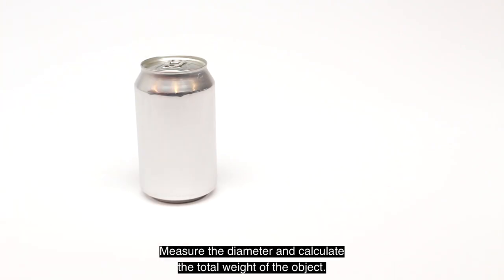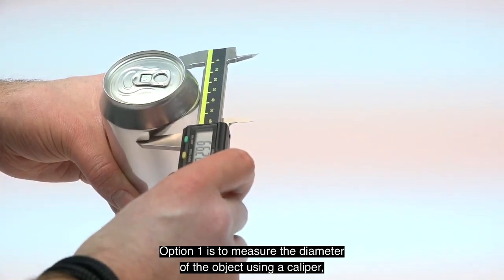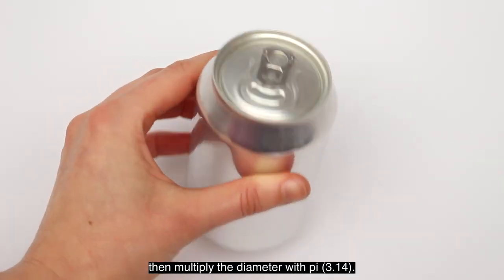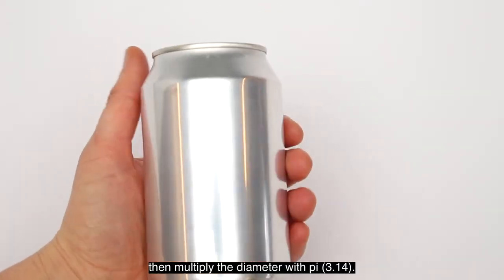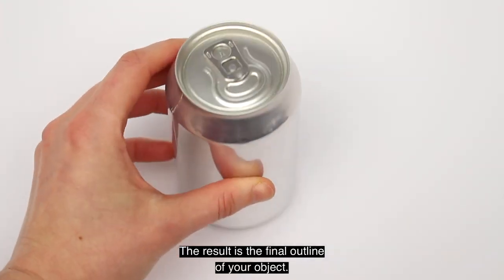Measure the diameter and calculate the total width of the object. You can calculate the circumference of the object in two ways. Option 1 is measure the diameter of the object using a caliper. Then multiply the diameter times pi, which is 3.14, and the result is the final outline of your object.